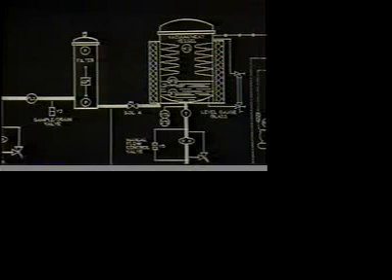Here we might have a sample drain valve. We go through a filter for filtration of particulate matter. After the filter, we send the contaminated lube oil to the top of this vacuum and heat vessel. We indicate here some heating system which surrounds the vessel.